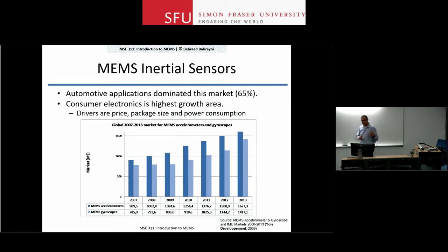And another reason, and actually one of the more important reasons that accelerometers are used in almost every situation where you have some sensors, is that they are very low power devices compared to a lot of other sensors. Nowadays, accelerometers consume microamps and give you meaningful data at such low levels of current, while a lot of other sensors actually need significantly more. Even gyroscopes that are needed in many navigation applications, for example, and are used in combination with accelerometers. Usually you're talking about milliamps versus microamps for accelerometers.